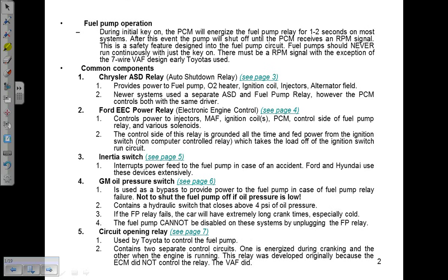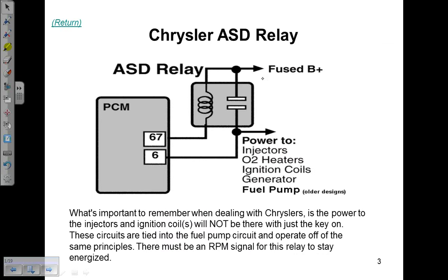ASD stands for auto shutdown. Provides power to the fuel pump, O2 heater, ignition coil, injectors, alternator field. That would be the brushes for the alternator. And newer systems are going to separate the ASD and fuel pump relay. So let's look at figure 3.